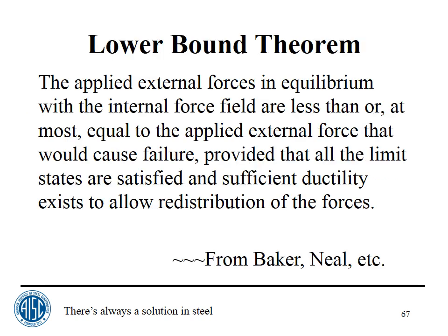So let's go on. I think that what Jim Wooten was really talking about here, although he didn't say it, was the lower bound theorem of limit analysis, which says that the applied external forces in equilibrium with the internal force field are less than, or at most equal to, the applied external force that would cause failure, provided that all the limit states are satisfied, and sufficient ductility exists to allow redistribution of the forces. This was from Baker, Neal, etc. This actual statement here dates from about 1952 or thereabouts.